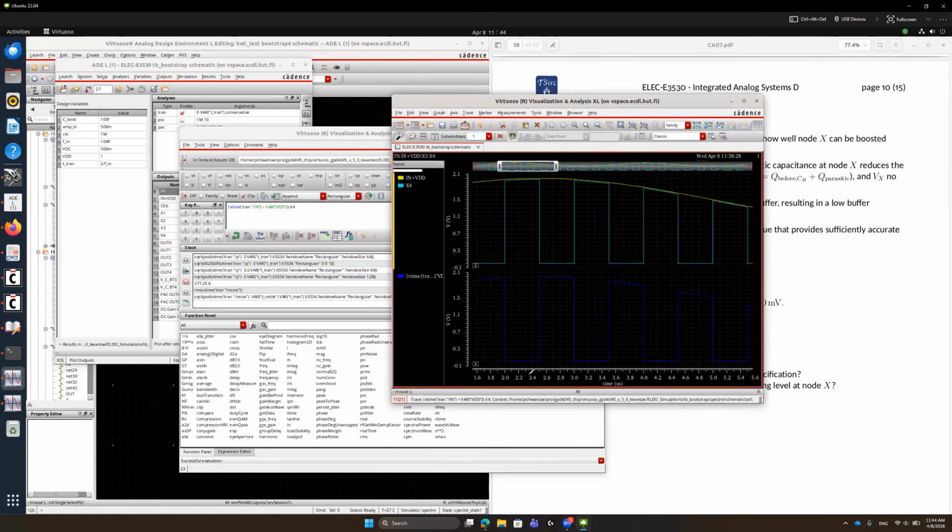And Vin plus VDD is always calculated no matter how our circuit is operating, reset phase, hold phase, or tracking phase, it is just simply Vin plus VDD. So X4 is reset, and even in that phase, there is some error.